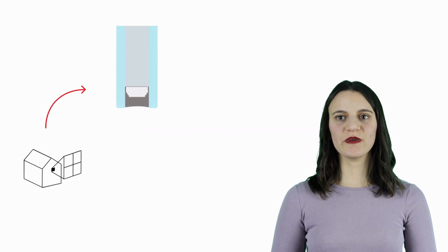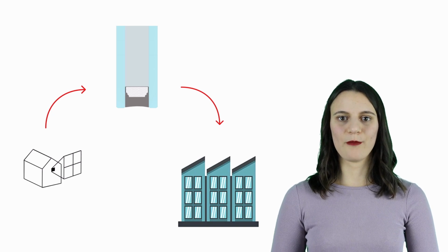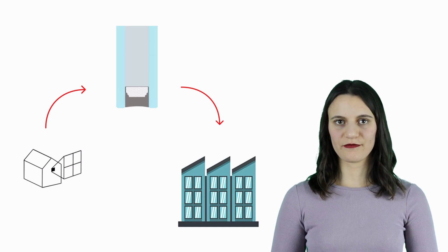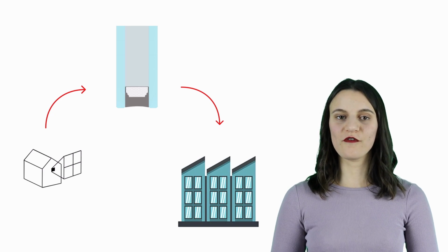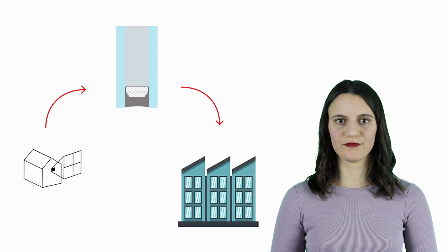Another strategy could be the reuse of the full insulating glass unit without disassembling. This operation seems easier and faster to carry out, as it doesn't include the disassembling, but the residual performance of the insulating glass unit, due to decreased gas content in the cavity, limits the potential application. The reduced gas content impacts the unit's insulation properties over its lifetime, making the strategy less beneficial overall.